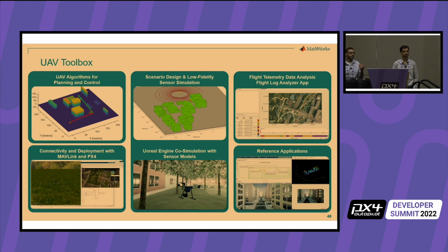But I have some customers who fork off the master, and they're able to do SITL, software in the loop, and hardware in the loop with MATLAB. If you want to work with newer releases, you would need some idea of the architecture and how PX4 works. You have to know how threads are called and build that interface a little yourself.